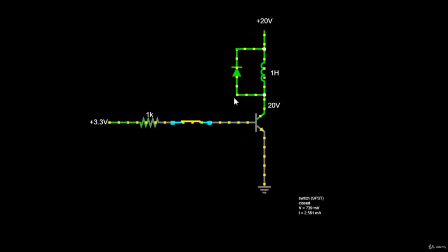So as you can see, the addition of a diode gives a path for the current to flow. Since diodes have almost no resistance when forward biased, the inductor only has to make a very small voltage drop to get the correct amount of current to flow. This prevents the switching device from arcing or being damaged.